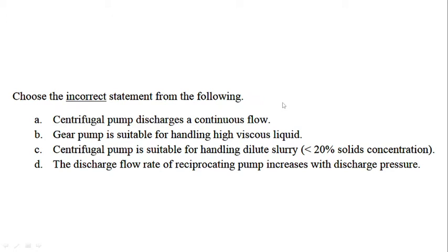There is a piston in the reciprocating pump, which moves backward and forward with the help of a crank to deliver high pressure fluid at low volume. And the flow rate is independent of the discharge pressure. It is dependent only on the stroke length.